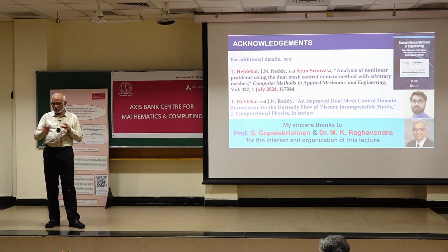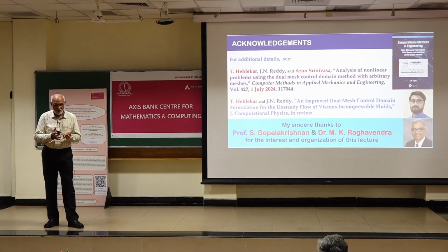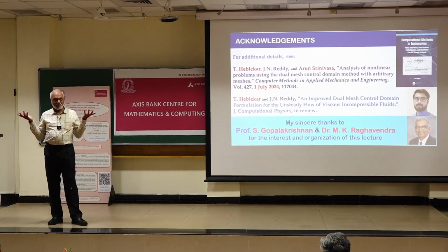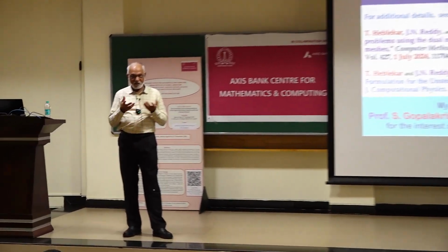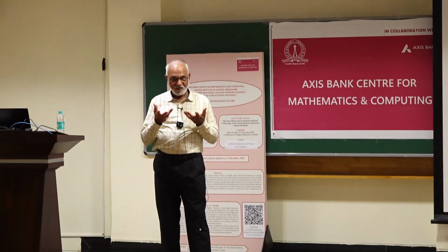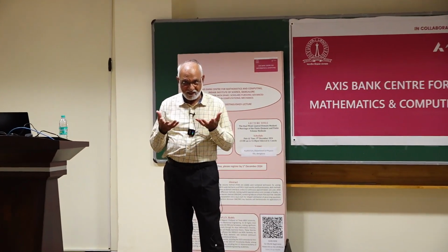But locking has nothing to do with the method. It has to do with the interpolation. We practice the same, that means we use different interpolation in the dual mesh. We don't use the same interpolation. If you use the same interpolation and lower order, locking will come. There is nothing you can do about it because you are not doing justice. It's like having a buffet.